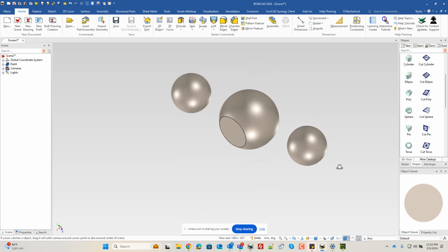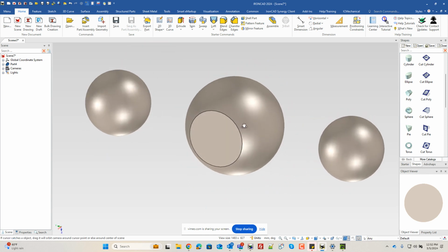Okay, so just a very simple way to move shapes around in space. Next, we can just drop our cylinder onto the center point of that face. And in this case, the diameter of this one needs to be 10, and it needs to be a depth of 19. So we'll select that handle and do 19 there. So we've got 19 here, 10 on the diameter.